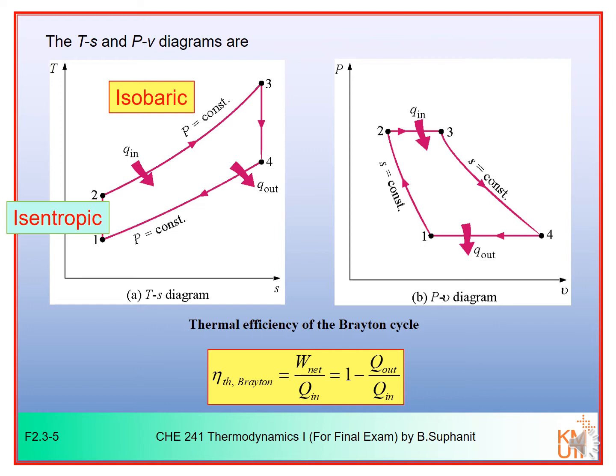So we have a temperature increase from point 2 to point 3. The flue gas, when it exits the combustion chamber, will expand isentropically through a turbine. After that, it will follow another isobar to cool down and complete the cycle at point 1 again.